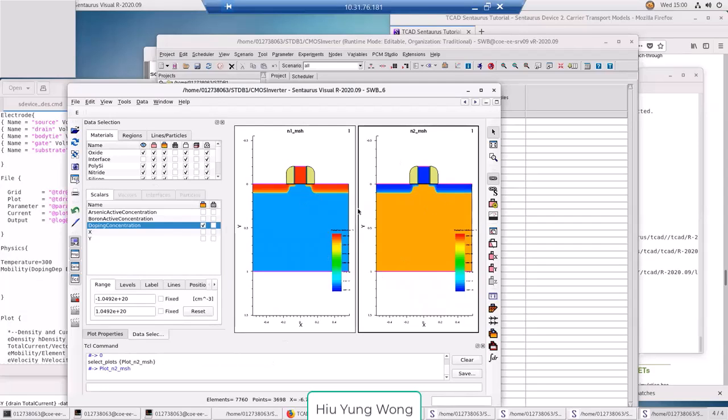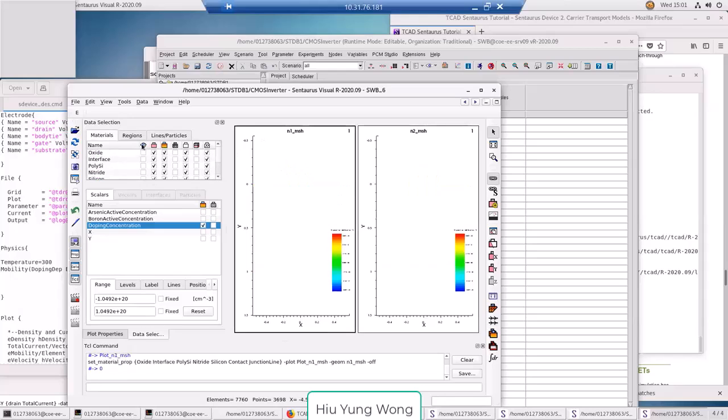So basically based on this, you know that, okay, it generated 2 structures. One is NMOS, one is PMOS. Of course, they all have their contacts. If you scroll down, they all have substrate, gate, source, and drain, right? I won't go into details. Of course, you can, like what I said last time, turn off everything, and then just try to inspect which one is gate, top is the gate, which one is drain, drain is on the right, which one is source, and which one is substrate. Just make sure everything makes sense, right?